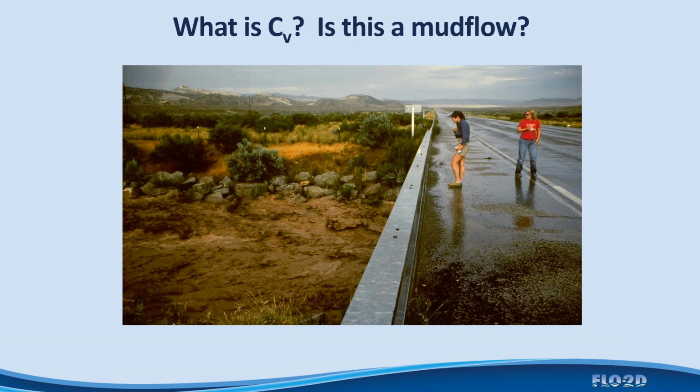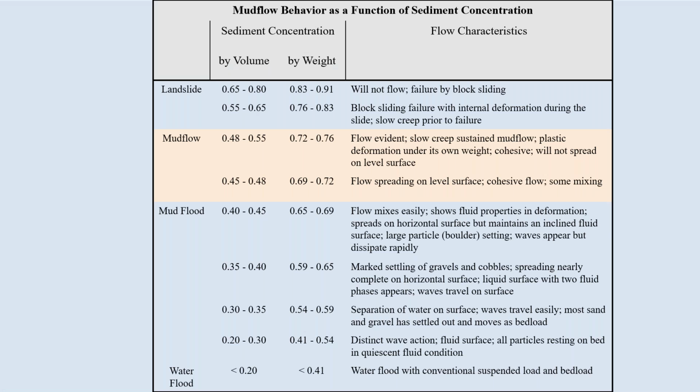If you had a flow that was on the order of 25%, you would be increasing the concentration by about 20%, or I mean the total volume and the peak discharge by about 20%. So when people design bridges and culverts and so forth for clear water flows and don't consider the potential, excuse me, of having sediment, at least 20% concentration by sediment, then you're missing about 20-25% of the actual design flow of the bridge. So most of your bridges are actually under designed in that regard.